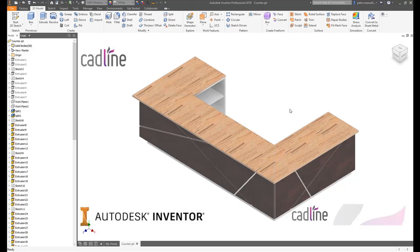You may or may not be familiar with this. If you are, then great. It's my preferred way of working inside of Inventor. However, if you're not, then you're probably used to working from a bottom-up approach, which would be designing a single part and then putting that into an assembly, designing another part, putting that into an assembly and constraining them together. This method works fine, and I still use this now and again, or where the top-down won't work. But 90%, 99% of the time I can make my models from a top-down approach.